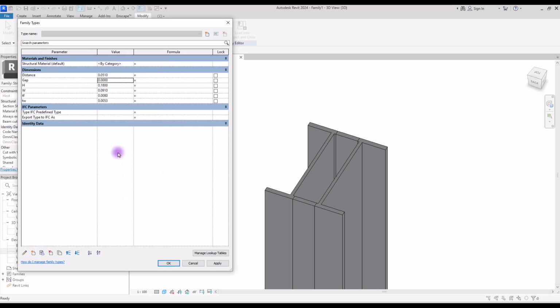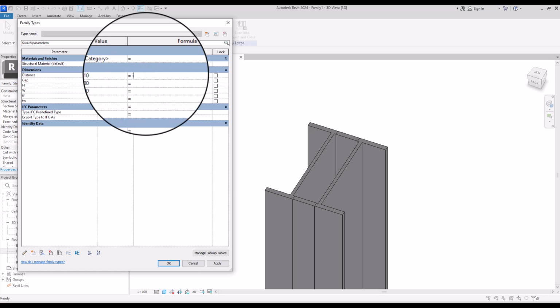In this part, in front of distance, we are going to write if, this gap is bigger than W, or this gap is equal to W, close the parenthesis. In this case, use W. If not, use gap itself and close the parenthesis.